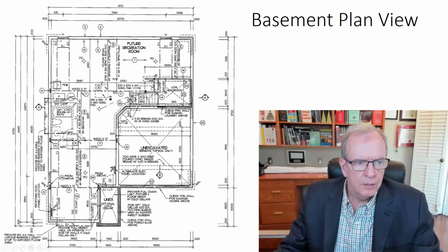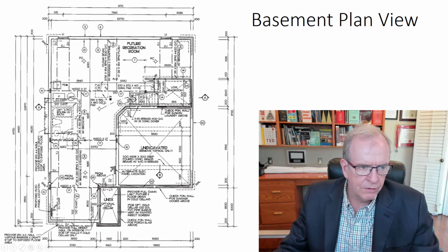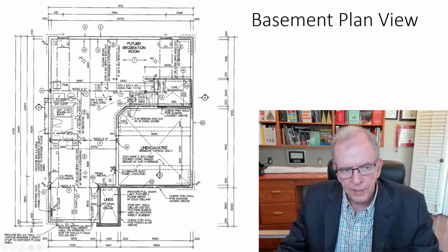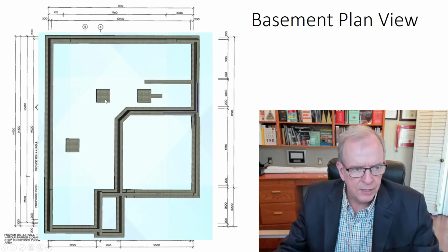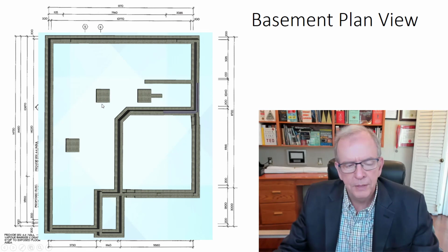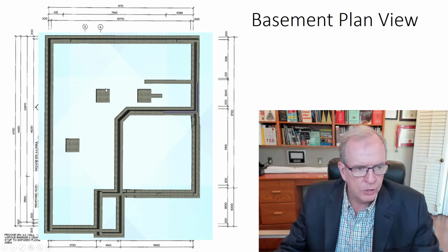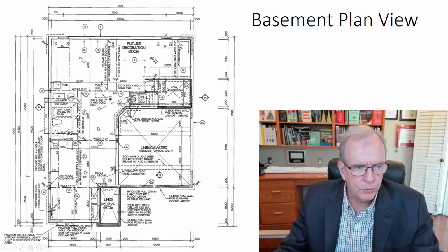All right. So we see that that's the floor joist size. We can see the size of the concrete footing, 990 by 990 by 460. So you're really looking at about an 18 or 19 inch thick pad here, almost 3 feet by 3 feet in area. You could do the exact conversions with a calculator: 25.4 millimeters equals 1 inch. But here's your pad, here's the other pad, and here's this one here. And so that's where you can find these.